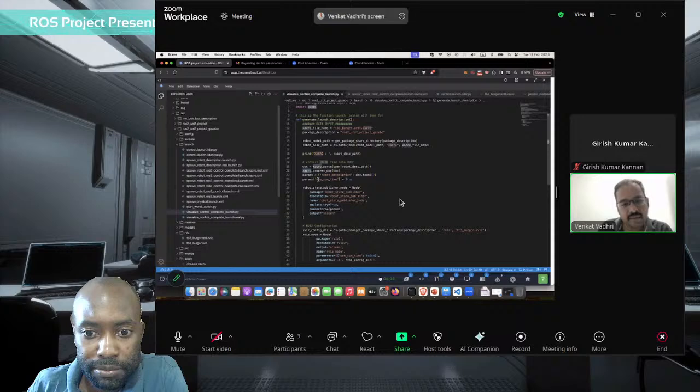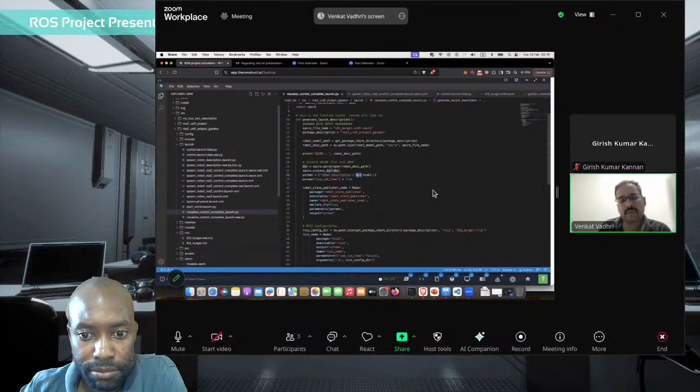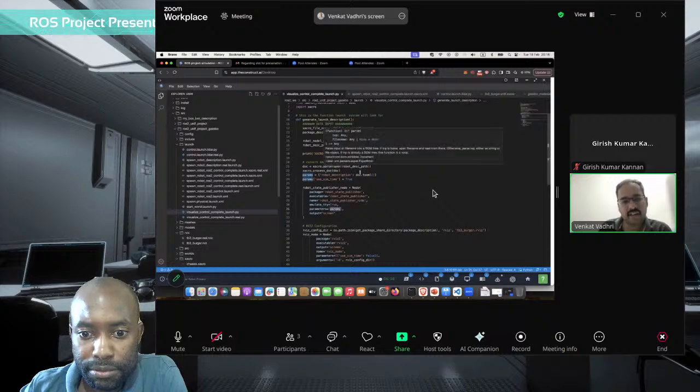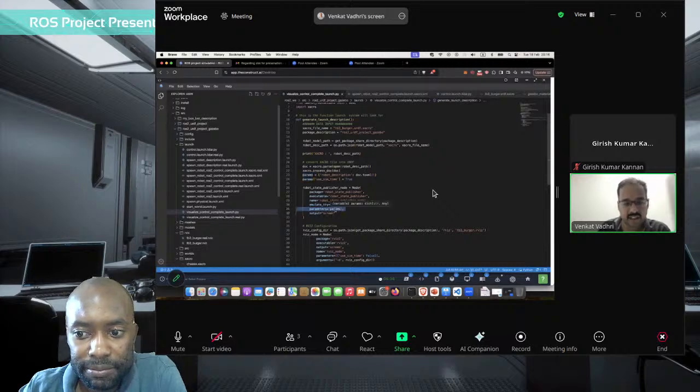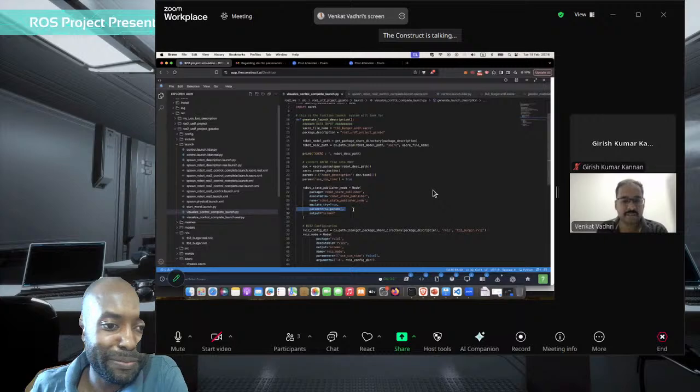The Xacro file. So basically, what I was doing is I was trying to pass in these parameters, and these parameters I wanted to give to this robot description to XML. This is in URDF. What I did not explore more and probably did some quick internet search was how do I give these parameters? And it looks like I found information where it said first take your Xacro file, convert it into URDF like this, and then give the parameters over here so that it works. If there is a better way, I did not go looking for it because it worked, so I left it there. All right, I'm happy I got to understand why you had to do it that way.